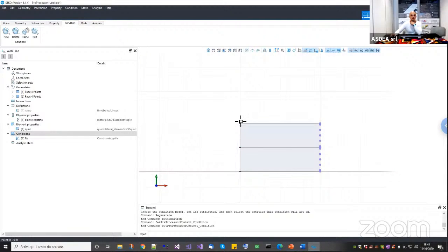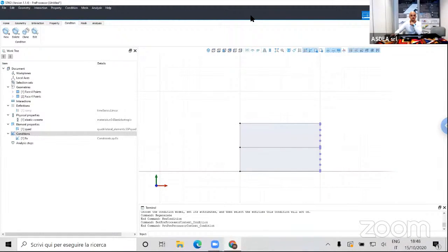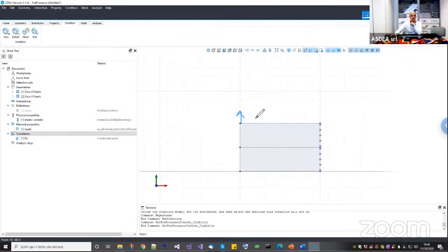And these two loads actually should be linear. So they should go, let me do a drawing here. They should go from a maximum of 1 megapascal here to 0 here, and then the opposite. So -1 and +1. And here I can show you how to do this kind of spatial dependent load in STKO.